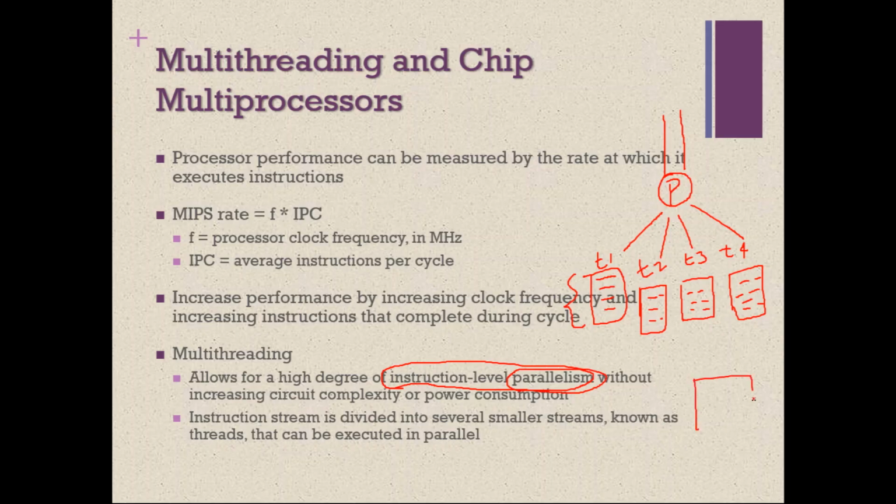The processor is only one, but inside this processor there is a pipeline, right? So let us say the processor uses a 4-stage pipeline as usual: the fetch unit, decode unit, execution unit, and write unit. But consider that this processor has 2 or 3 execution units. Okay, there are 3 execution units inside the same processor: E1, E2, and E3.